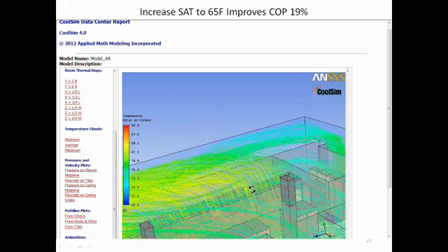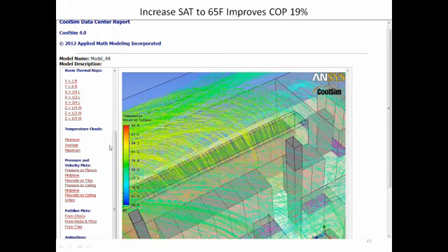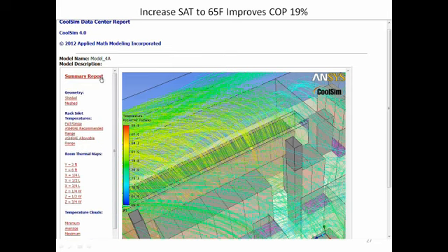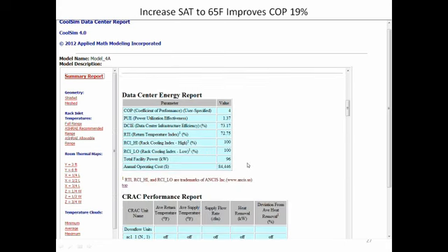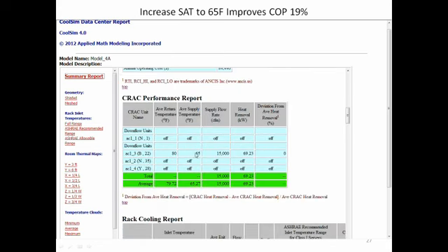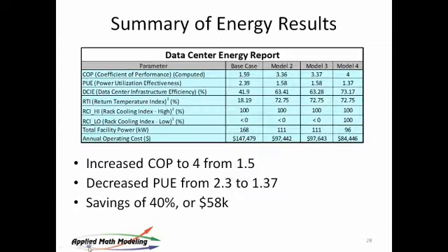These get a little busy with a ceiling plenum return, but as you zoom in, you can see the hot coming straight up out. The hot temperature, if we take a look at the return temperature in our summary report, is in pretty good shape. Let's take a look at our return temps here, and we see, yeah, we've got a 15-degree delta across. That's pretty good. We'd love to see 20, but 15 is not bad. We'll take it. And so that's our best case.